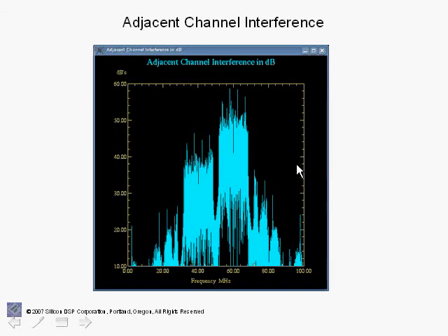Another issue that we deal with is adjacent channel interference. For example, here we're showing the desired channel and an adjacent channel, in which the adjacent channel is transmitted with a higher power than our desired channel, and we will talk about the issues involved in combating jammers and interference in OFDM systems, in particular the trade-offs between filtering in the analog domain and the digital domain, and we'll talk about how to prevent aliasing and so forth.